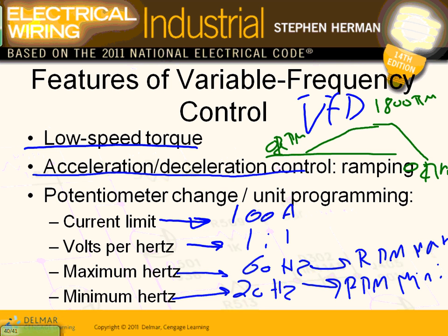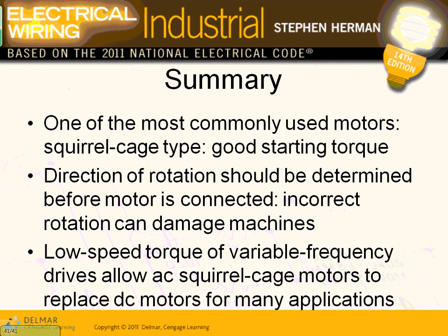And at the same time, the speed of the motor goes slower, slower, slower. Within 10 seconds, it comes to 0 voltage, 0 speed, versus you push the button off and it cuts the voltage immediately. So it takes 10 seconds to ramp it down. All this, guys, will make smoother, better operation for equipment. That's really the whole idea.